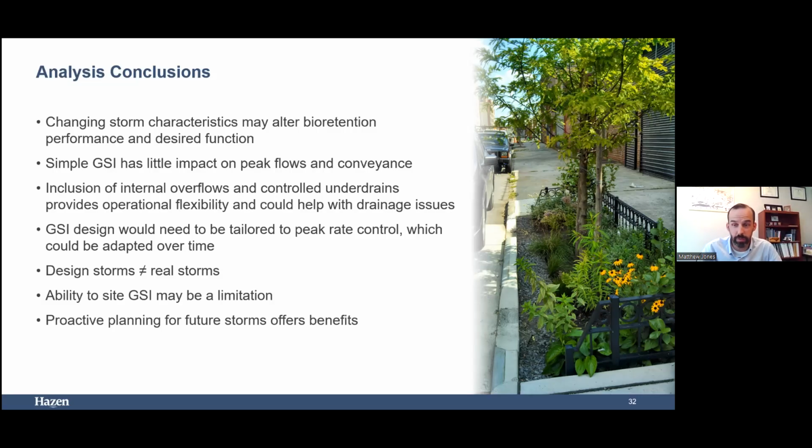And related to that, where we're seeing, I think, nationally, the most interest in implementing green infrastructure in this capacity for drainage relief is where you have highly constrained environments, or you have constraints on where you can upsize maybe a length of pipe, but you can't carry that all the way downstream. And something where green infrastructure with the design modifications we discussed here can help provide some of that detention to help facilitate addressing those issues.